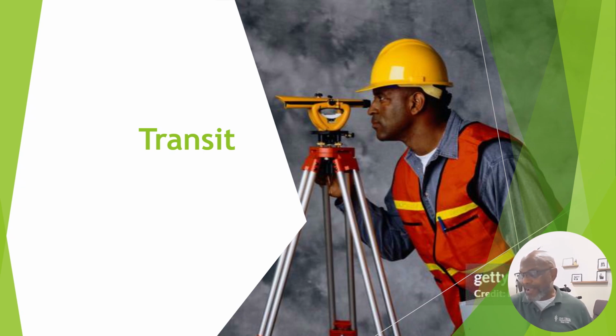So read the angle in the same direction it was turned. Observe the direction the angle was turned. Everything is to be read in that same direction. So in other words, when you start one direction, continue moving in that direction. If the angle was turned clockwise, the vernier and the circle must be read clockwise.